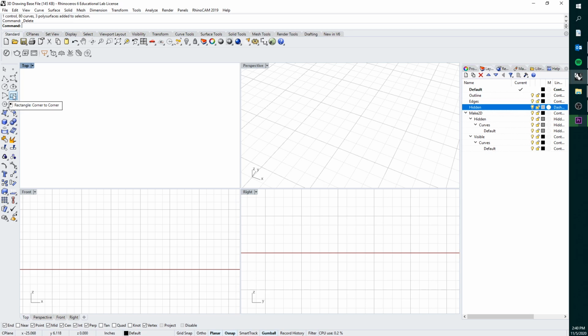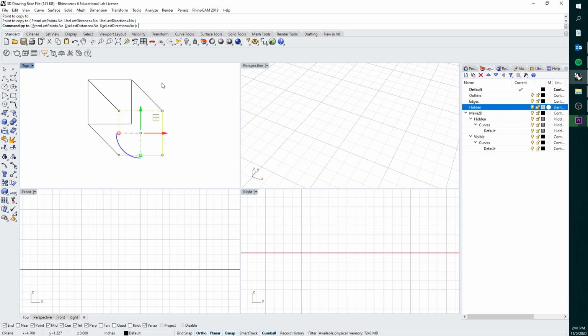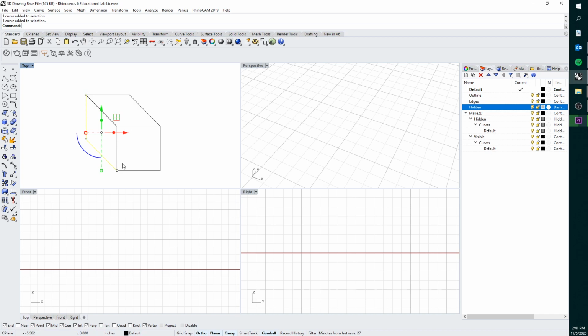We're just going to look at how you would actually construct this drawing. So if we're looking at this in elevation, then what we would want to do is draw with our ortho on. We're going to draw a line at 1 inch, and then we're going to rotate that up, so -45. Then we're going to copy that around to our endpoints, and then we're going to copy this guy back. And then here, if we just do a simple explode on this, what we would end up with is a measured drawing here, so all of our edges are actually the right dimension.